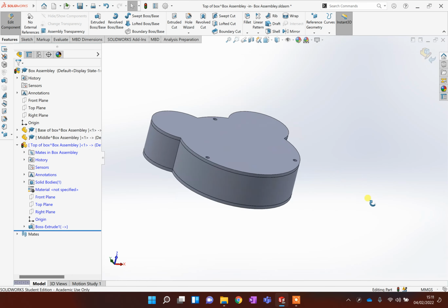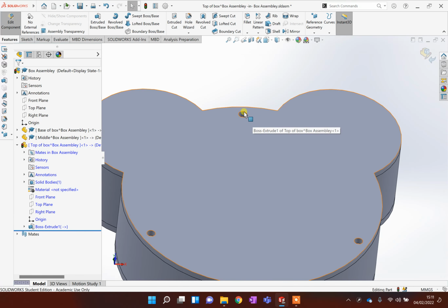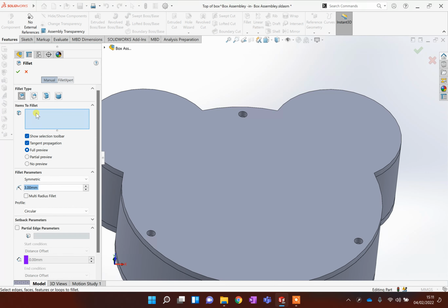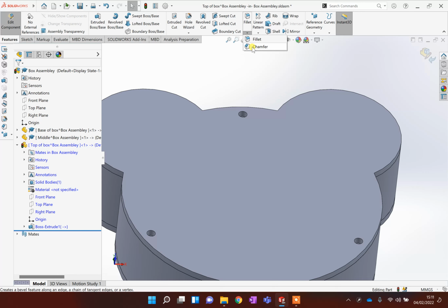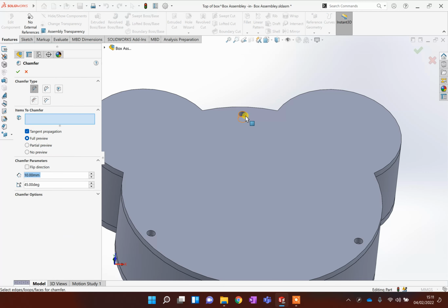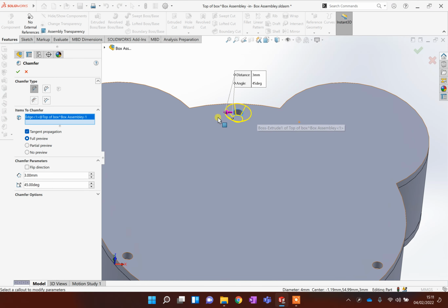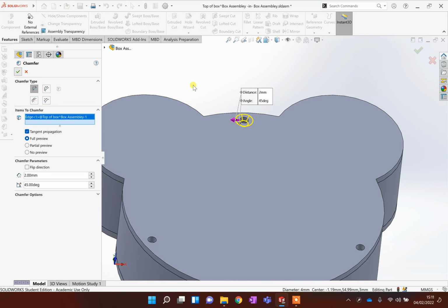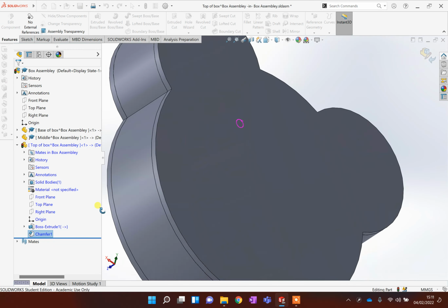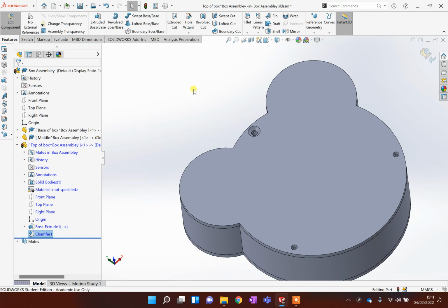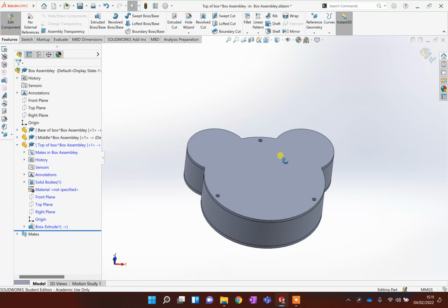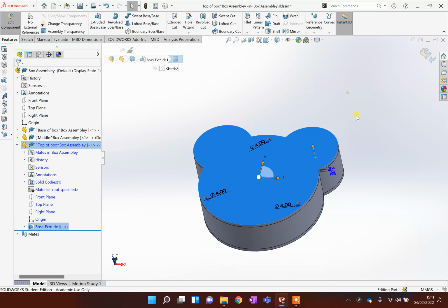Now, in the workshop, what we'll actually do is we'll put a little countersink in here, which is like an angled cut. So in the workshop, we'll actually drill in. I don't want you to model it because if you model it, it will come out wrong on the laser cutter. But we're going to put a little chamfer on there in the workshop, say like, I don't know, 3 millimeters. We'll actually drill a little hole in, something like that. And then the head of the screw, just to give you a preview, will be sunken into the box so it'll fit nice and flush. And then we flip it over and there's your box. But I don't want you to do that on the model, please, because we are later going to take this and export it for laser cutting.